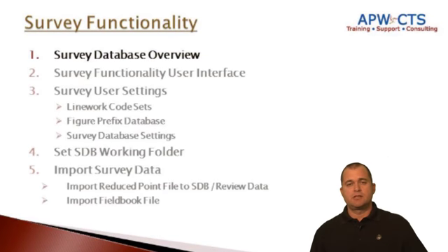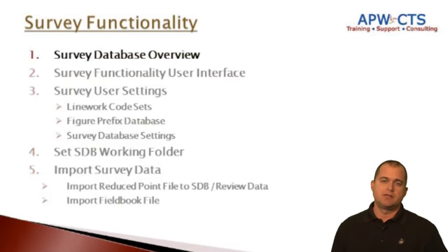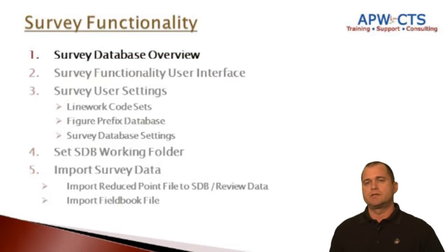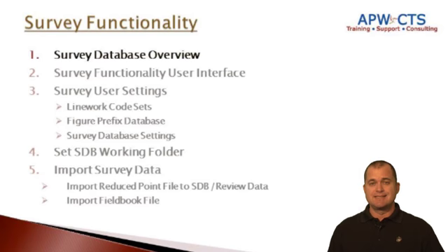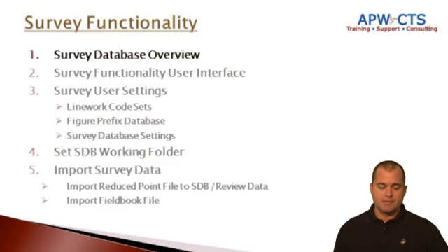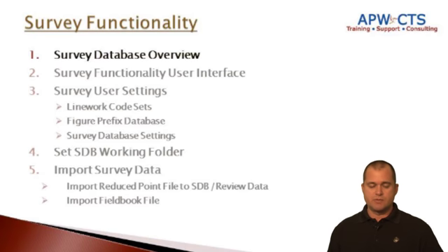All right, so beginning of the survey lesson, we're going to provide just a brief overview of what the survey database is. The survey database is actually a separate set of files and a separate proprietary file that exists outside the drawing of a Civil 3D drawing. With the survey database, you can open up any drawing and then create and import data to and from that survey database within that drawing.